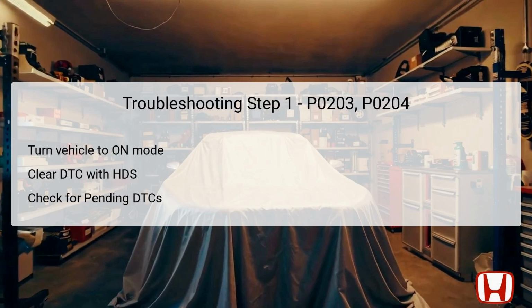The first step in troubleshooting DTC P0203 and P0204 begins with verifying the problem and preparing the vehicle for assessment. Start by turning the vehicle to the on mode without starting the engine. This enables the diagnostic tools to communicate with the vehicle's systems. Next, clear the DTC using the Honda Diagnostic System, HDS. This step ensures that you are starting with a clean slate to accurately assess if the errors reoccur.